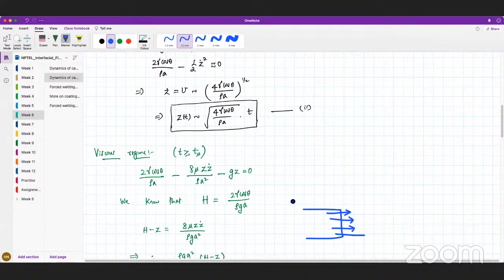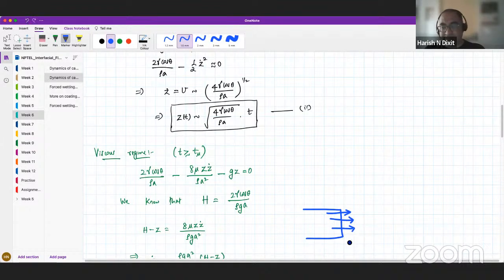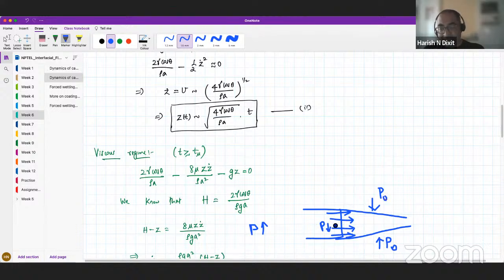Now, it's exiting at very high speed, but you are also starting with a very high pressure gas. So you have a high pressure gas here, so P is very high here, and P is low here. Now, if this pressure is lower than the atmospheric pressure, then when it exits, the gas actually comes inwards, simply because the atmosphere is actually pushing it inwards. This is the P exit.